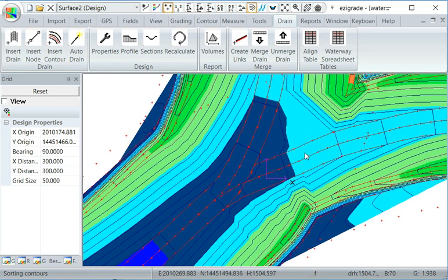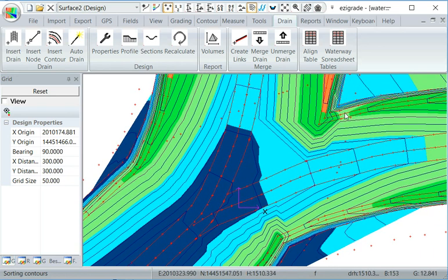You can also see there's a couple of little issues here. This is just not a problem with the program as such. This is trying to get the second drain to match the first one, because we've only got heights here of 4.5 feet and these were 9 feet. So this is why you've got this dip down and then it starts going back up the hill again.